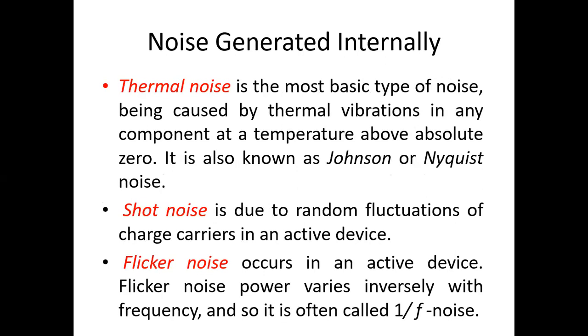It is normally not considerable in most circuits, because in the circuit you work with pretty high voltage level or pretty high power level. So the small fluctuations from thermal noise you can ignore. Your results will not be significantly affected. The power level from thermal noise is very small, so you can ignore it for ordinary computations.